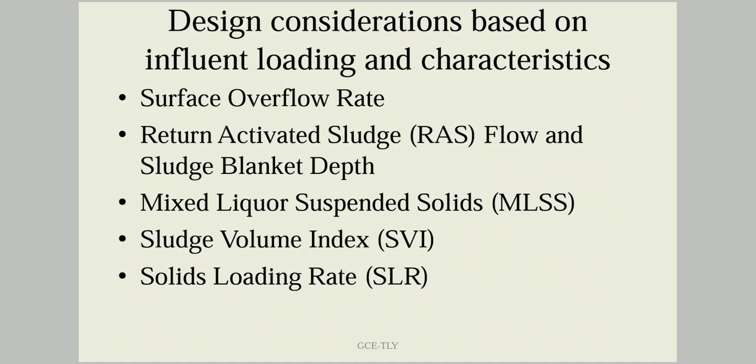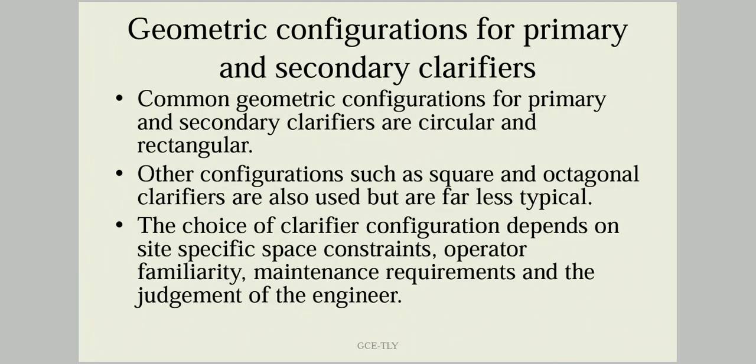Based on the influent loading and characteristics, the following are considered: the surface overflow rate, the rate at which the effluent is treated; the return activated sludge flow and the sludge blanket depth which is formed; the mixed liquor suspended solids or the food to microorganism ratio; the fourth one is the sludge volume index; and the fifth one is the solids loading rate.